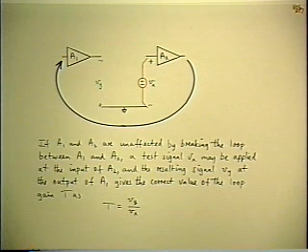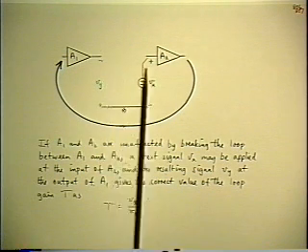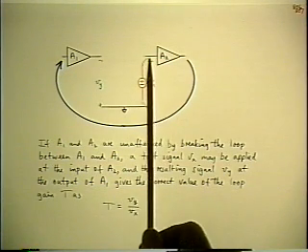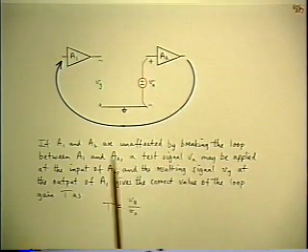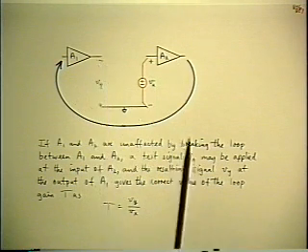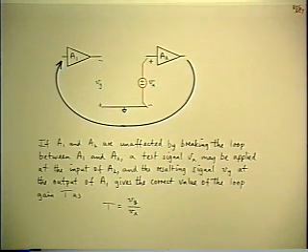One little point about this before we go on. Notice the choice of polarities. If I define Vx as positive, it will show up in the other direction on the other side of the break if the feedback is negative. And that's the case that we want to consider. Or qualitatively, in other words, if the voltage Vx goes up a little bit, the voltage Vy goes down a whole lot if the loop gain is large and negative.